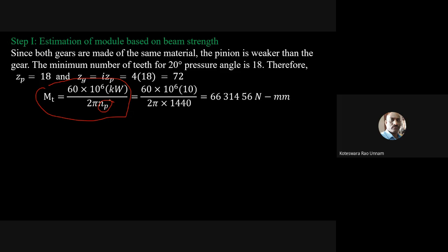Addendum is nothing but 1 module. Whatever may be the module value, that is going to be the addendum. Then if you flip the next page, he has given addendum for the standard tooth HF, which is 1.25 m, tooth height 2.25 m, height factor 1 for standard teeth, 0.8 for sub teeth, like that he has given.